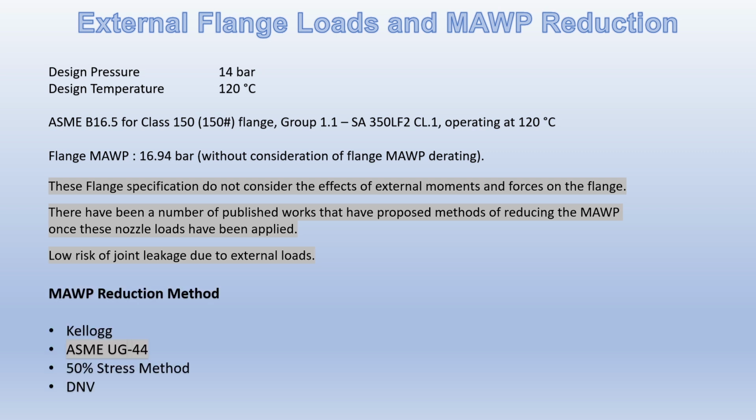There are about 4 types of MAWP reduction methods. We will explain the method that we use the most, which is the most requested by the client. It is according to UG-44B under ASME Section VIII Division 1.